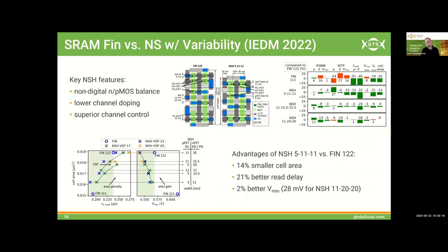Also, you can start looking into different standard cell optimizations. For example, if you have the question, is a FinFET technology or a nanosheet technology more suitable for what I'm designing for? What are the trade-offs between those technologies? And how can I optimize or change my design or down select my design choices in a specific manner?